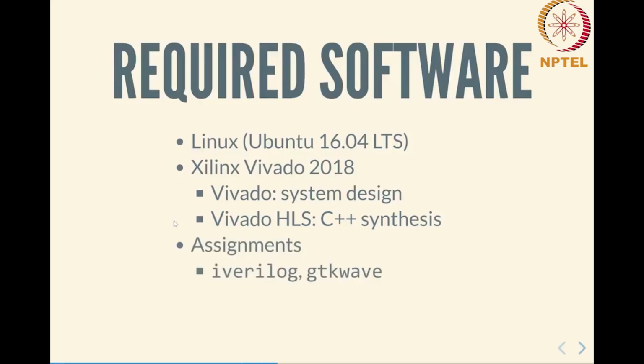For the assignments, in some cases, you may be able to use tools such as iVerilog and GTKWave. The reason I mention these is because they are much lighter and faster tools for small assignments. Although for large assignments, you may find that the Xilinx tools are actually better and easier to use. For small, simple test cases that you want to write with Verilog, the overhead involved in starting up the Xilinx tools can be quite significant.